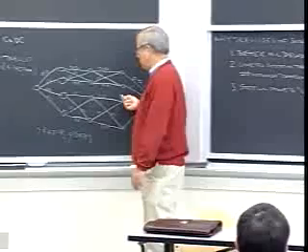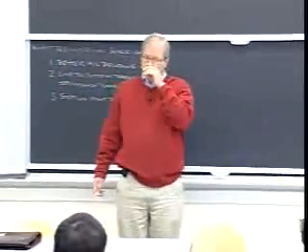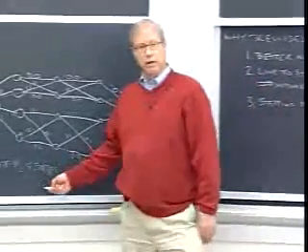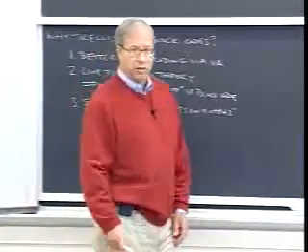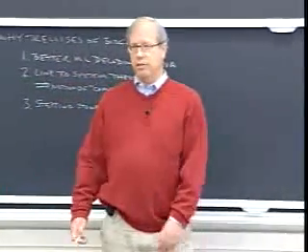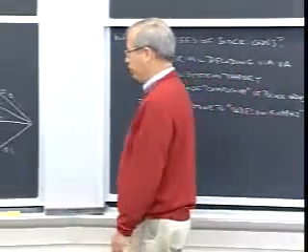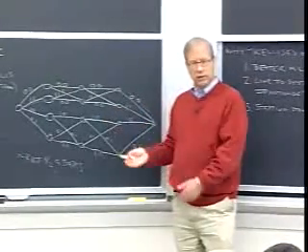You could decode this with a Viterbi algorithm, and you could see the complexity would be comparable to the complexity of decoding a rate 1/2 4-state convolutional code. And in fact, you remember I compared our example rate 1/2 4-state convolutional code, which had a coding gain of 4 dB, with this code, saying they roughly had the same complexity.